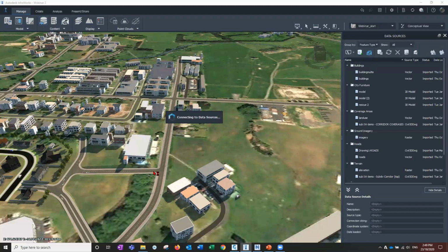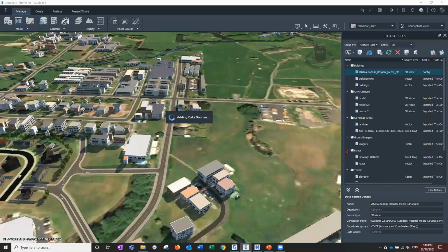How can I import a surface from Civil 3D to Infraworks and have it adjust? So a surface imported from Civil 3D, not sure, I'll bring one in a moment. You can actually find them in the data sources. So you can right click on it and there's a re-import button in the right click menu. That should update your model. As long as you haven't renamed it, it'll reference the Civil 3D model. You do need to be reading the drawing though.